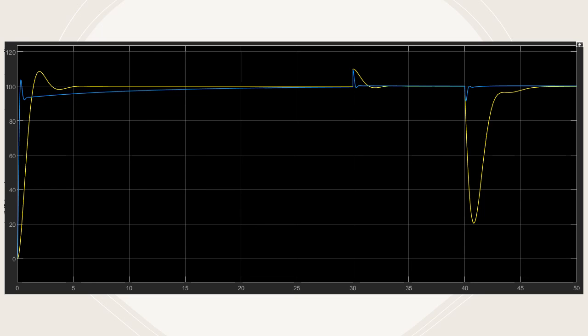This response shows the principal reason of existence of the Cascade controllers. It allows for disturbances to be attended simultaneously at different points in the plant, while achieving a fast rejection of disturbance before it propagates to the other parts of the plant.